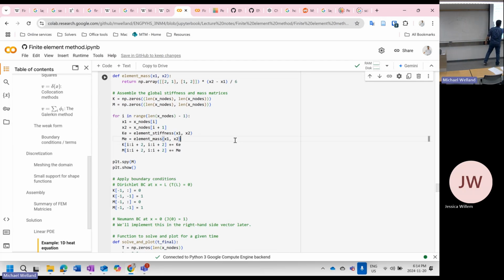That's what this is doing. You're calculating that block, and then you're just adding it. You're not replacing it. You're just adding it. Integration is all additive because of its associativity. So you take that and you add on your mass matrix and your stiffness matrix. You move on to the next one and you overlap. Mass matrix, stiffness matrix, and you overlap again, right?